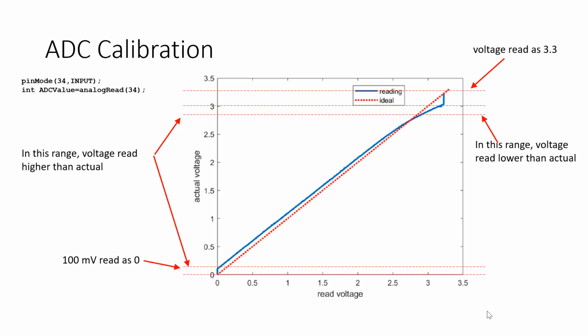So then once you walk through those ranges, you tell the power supply to start paying attention to the front panel controls, right? You release control of the power supply, and then when you demo your project, we can go up and make adjustments on the power supply, and then your console will print its interpreted value, right? And then we can figure out how accurate your code is. Because if I dial the power supply to say 5 volts, I'm going to look at your console, and hopefully it'll say something around 5 volts, right? Because your calibration model will be correcting it.